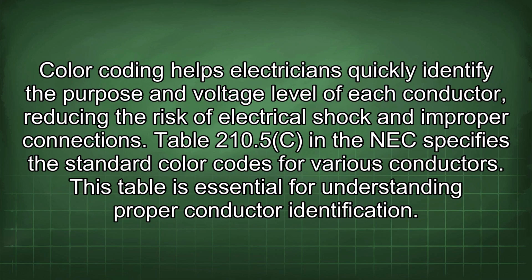Color coding helps electricians quickly identify the purpose and voltage level of each conductor, reducing the risk of electrical shock and improper connections. Table 210.5c in the NEC specifies the standard color codes for various conductors. This table is essential for understanding proper conductor identification.